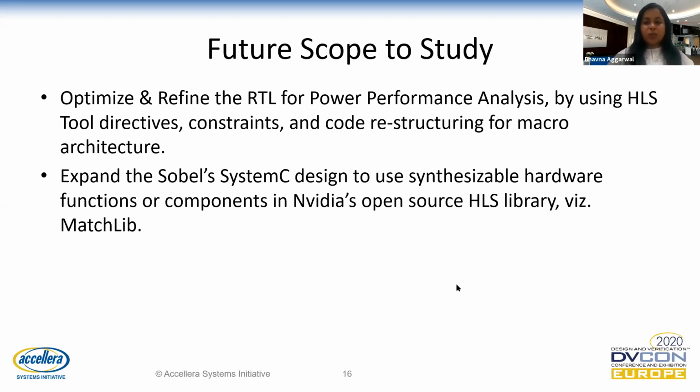I hope till now I could illustrate the benefits of high-level synthesis in terms of automated RTL generation from an open source C++ design and providing a co-verification platform for functional equivalence of the software versus hardware. To emphasize, a software practitioner can easily take the original software implementation and generate a functionally correct RTL without requiring in-depth knowledge of it. They just need to understand the synthesizable subset guidelines, which are actually easy to understand.